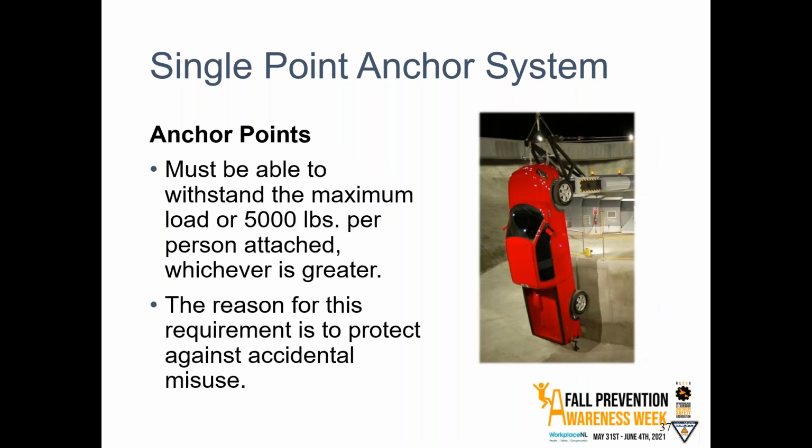With regards to anchor points, they should follow all the same rules that we would use for fall arrest. So the anchor point, in a way, could be considered to be two things. It's the structure that you're tying off to. So that could be, you know, steel or wood beams or who knows. It certainly shouldn't be anything flimsy that you couldn't support your weight.